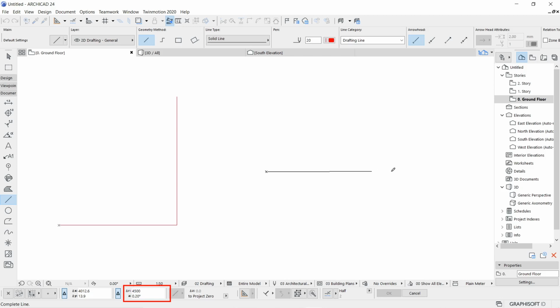And the direction which I am going to travel is towards the east side. That is from the pick point, the right side or east side, equivalent to 0 degree. So I'm going to press A now from the keyboard and I'm going to press 0. So this becomes my first data entry done by the relative method.